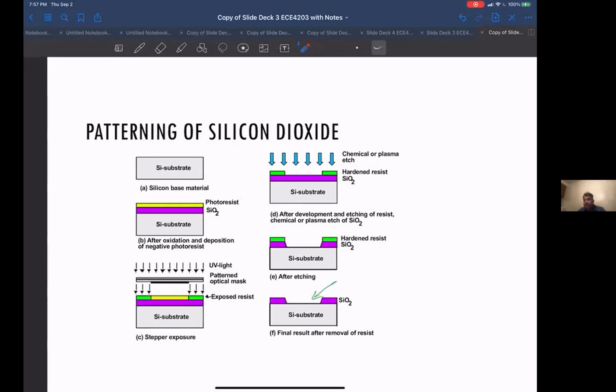And then on top of the silicon is the metallization. There are different layers of metallization to connect these transistors that you've created. All the tools they have there are oxide deposition, metal deposition, lithography and etch. They're using masks and photoresist, but it's a multi-step process.